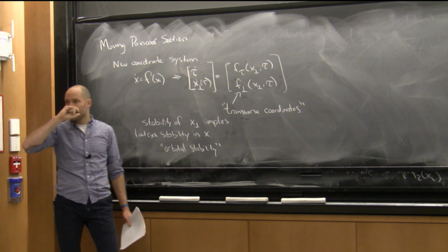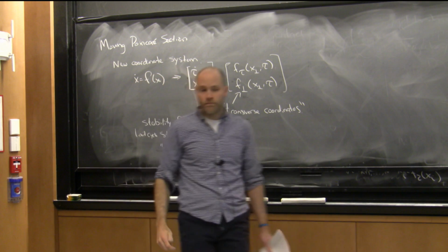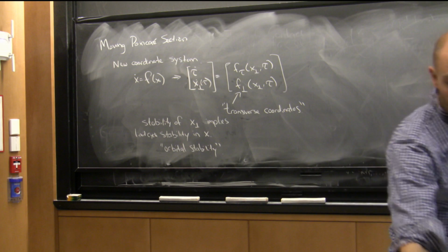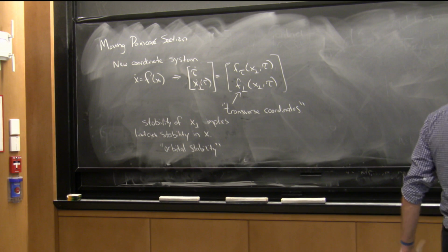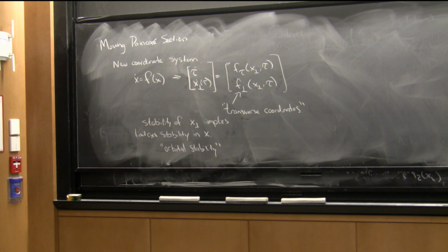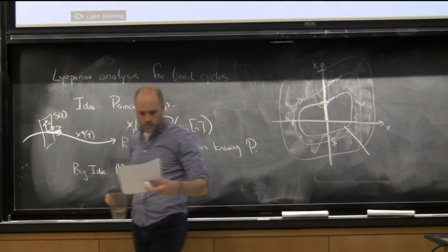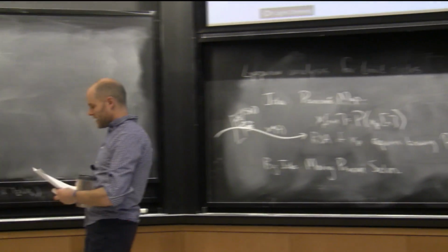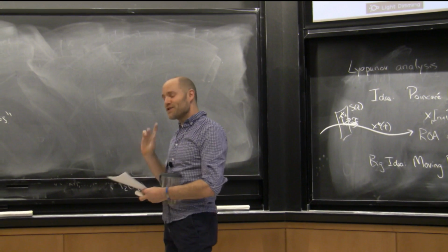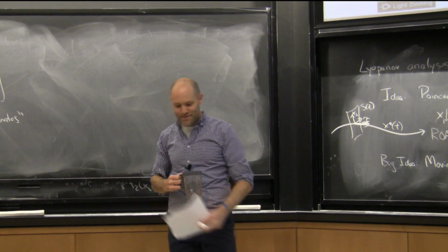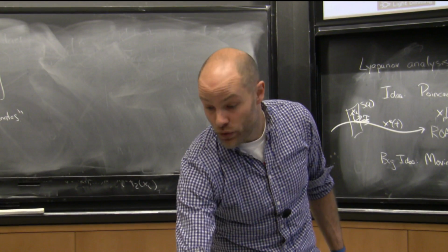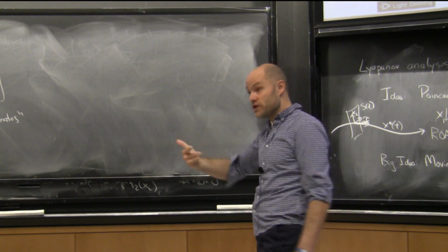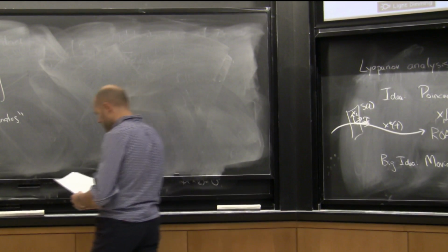Yeah? So is there any sense of local or global stability, or is this completely different? It's completely the same. Local stability means epsilon away from the trajectory. In fact, I think it's my next page. I will tell you local stability, global stability on the very next page. Completely the same. And regional is the other one in between. If you have a region of attraction, that's regional stability.